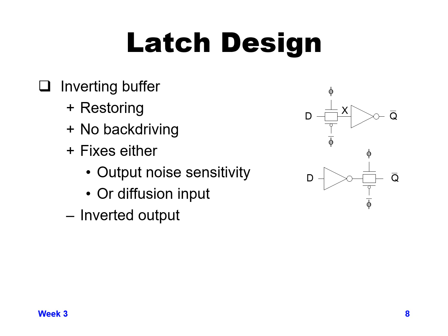Now, the one additional con to this design is that your output is an inverted value. Instead of being a pure buffer, you now have an inverting latch design. In some cases, this may not be a concern to you. You might actually be able to use this inverted value. So it's not always a con, but it could be a con depending on your implementation.